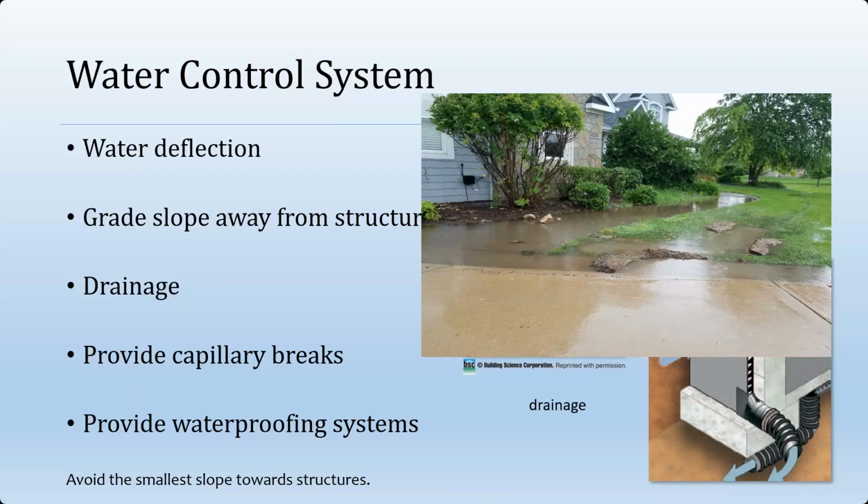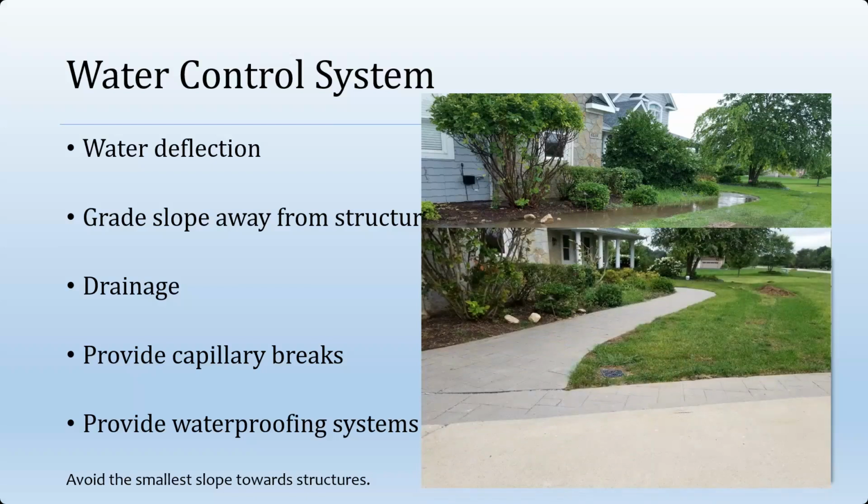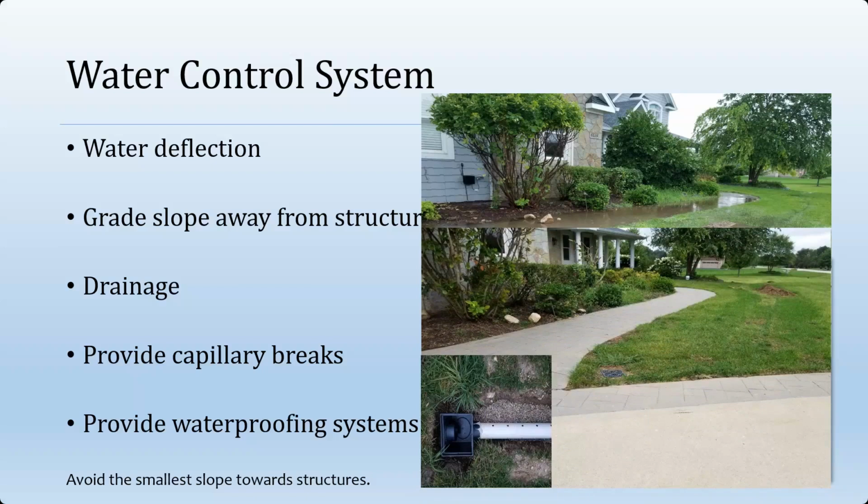And in fact, when I basically hand dug this trench, tied it into a 1 square foot box drain, and reached the bend in the front walk, that is when I discovered that 90-degree elbow. And when I unplugged that elbow from the ABS slotted pipe, I unearthed probably about 18 inches of ceramic roof granules that had plugged it, and all this water rushed out. So it was pretty dramatic.